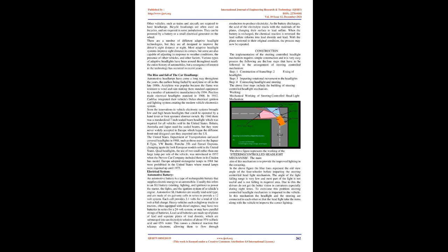Steering system. The primary function of the steering system is to achieve angular motion of the front wheels to negotiate a turn. This is done through linkage and steering gear which convert the rotary motion of the steering wheel into angular motion of the front wheel. It also serves to provide directional stability of the vehicle when going straight ahead, to provide perfect steering condition, i.e., perfect rolling motion of the road wheels at all times, and to facilitate straight-ahead recovery after completing a turn.